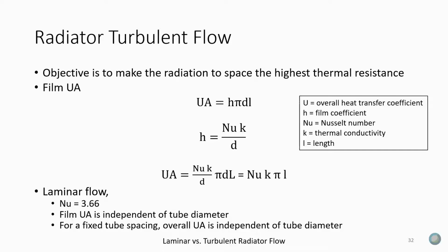And so once you get into laminar flow, a couple of things happen. Once you've got your tube spacing set up, normally we do our tube spacing in the radiators at about 4 inches or 10 centimeters, because that just works out to be about the right number, gets you high radiator fin efficiency without getting, I lost my train of thought. I was looking at the screen. I'm sorry. So, 4 inches gets you not too heavy, because you can keep your tube size reasonably small, but also keeps your fin efficiency up.